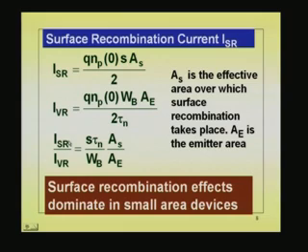If I_SR is equal to volume recombination, you do not have to worry, because we found out that the beta decided by volume recombination is very large. The ratio of I_SR to I_VR is given by these two terms cancel, Q N_P0 gets cancelled, and S is there. A_S by A is written here, and tau_n goes in the numerator because we are dividing by that, and W_B is in the denominator. So, just cancelling the common term N_P0, you get this.